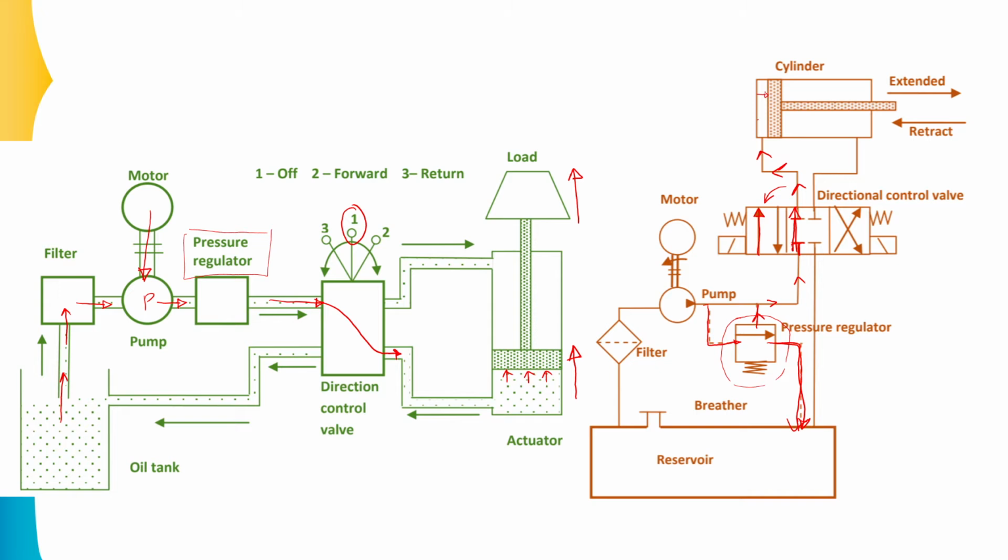This cylinder will be pressurized from the bottom, and this pressurized cylinder will basically move this load in the upward direction. At the same time, the oil that is available on the top of the piston will be returning back from this pipeline. In this specific diagram, this is the returning oil, and it will return in this path. As you can observe, this is the path.